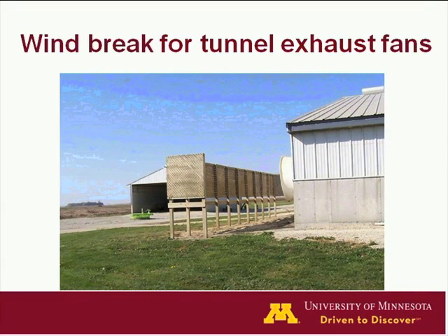Finally, I think Kevin did mention that when we're talking about what the fan has to work against, again, the static pressure, the wind forces that are blowing against the fan from the outside actually create a static pressure as well. And in some particular cases, like on the end of a barn that has all tunnel exhaust fans, some windbreak fence, like shown here, can be helpful in trying to reduce that effect under certain weather conditions.